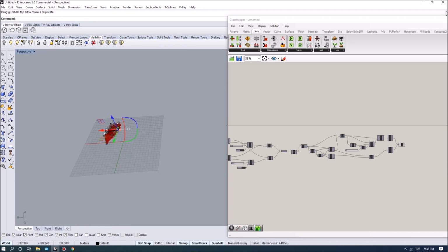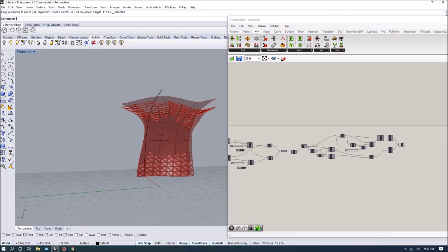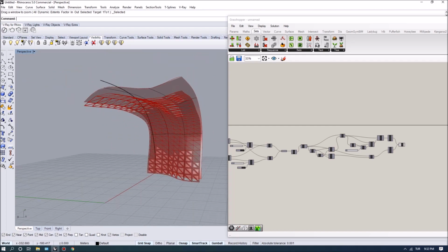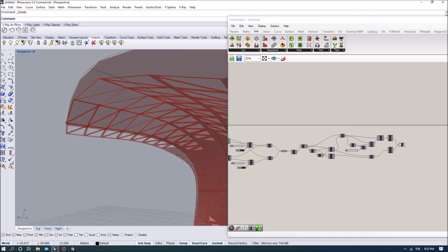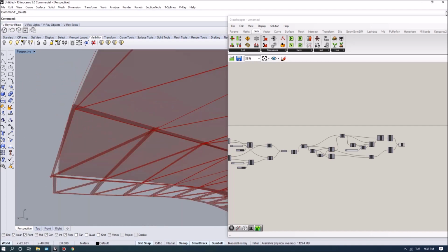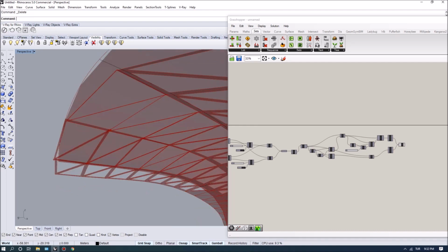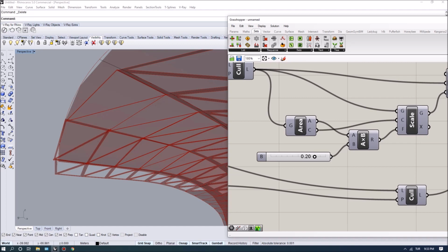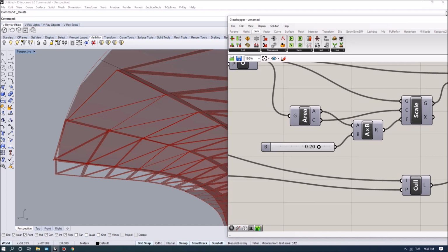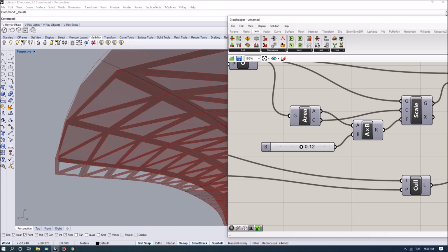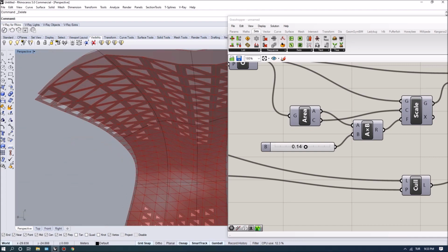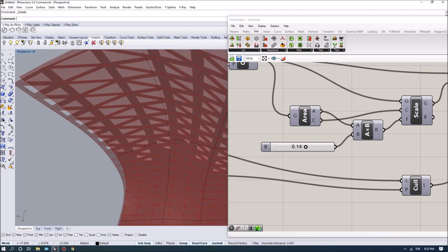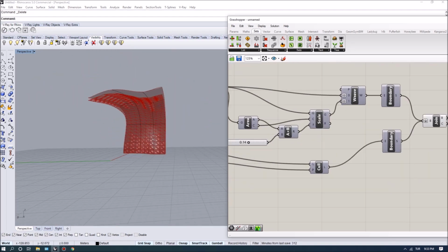So I'm trying to maintain a nice shape for the surface, but basically this whole variation will be driven by the surface topology. I'm going to delete the input curve that I had, because now our surface is run by the parameter. And here I have an issue which comes from the scaling down. Because the scaling is too much, the boundary surface is not executed correctly, so you can decrease this percentage a bit more so that you can get smaller gaps, but here you wouldn't get any errors because those tiles are really big. So let's bake some variation.